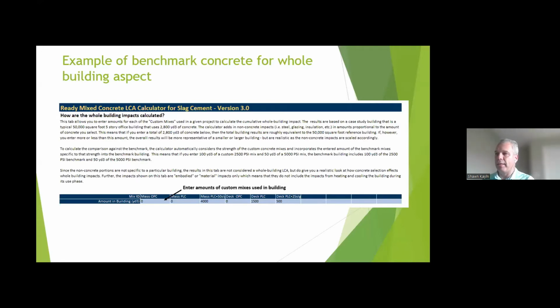And then in some applications, there may be times where they may be able to put more slag into it. It may slow down the 28-day strength, but they may not need any strength until later on. So in those aspects, you might be able to change it. So you as a designer and as a contractor could have multiple mixes of that same one that have a different varying amount, and would be able to see through the lifespan of that job how those change. Because as we all know, and how contractors and designers can be, a job might be meant to be starting in July, and next thing you know, guess what?